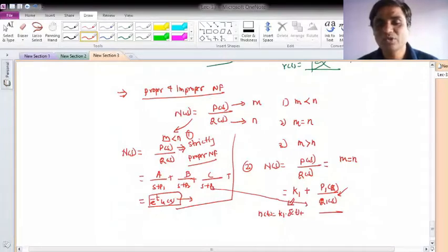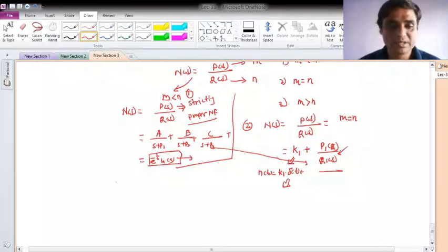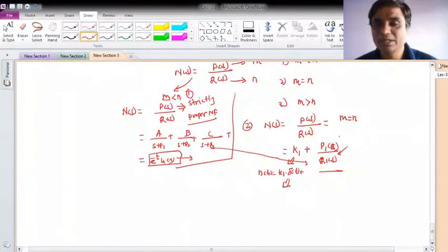So what I observed here is that I am getting the impulse function, which is not at all good. If I have obtained a network function where the degree of the numerator is equal to the degree of the denominator, then there is a presence of impulse, which is not good, as we have discussed. This kind of thing is called a proper transfer function, not strictly proper, but proper.